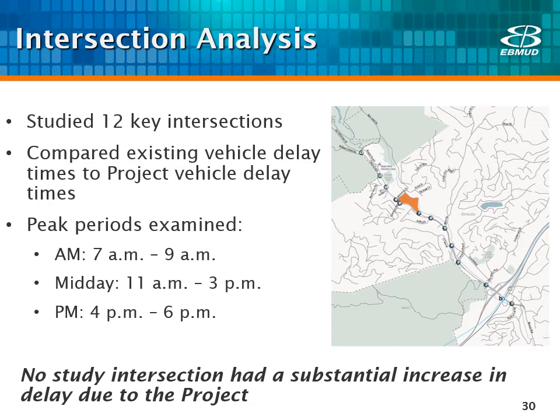The intersection analysis, also known as a level of service or LOS analysis, compared existing vehicle delay times in seconds to project vehicle delay times. The peak periods studied were the morning peak period from 7 to 9 a.m., the midday peak period from 11 a.m. to 3 p.m., and the afternoon peak period from 4 to 6 p.m.